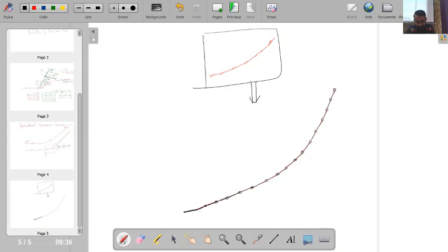So what I have done, basically, I have a curve. This curve I have fitted with small lines, and each line is showing some deflection angle. For example, here this was coming straight, so after this, the deflection angle is say d theta 1. Then it was going in this direction, and then I have deflection over here, so say this angle is d theta 2. So I have divided the whole curvature into small theta i's,